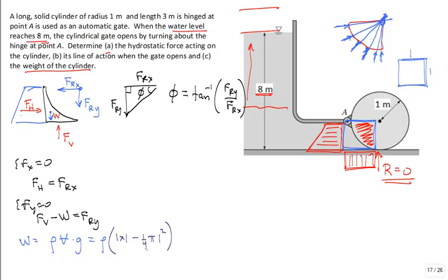That makes sense? Don't go to sleep on me. Are you with me? That's right. And then we have the depth of 3 meters. Put 3 meters. Put 1,000 kilograms per meter cubed, and then 9.81 meters per second squared. And then you calculate the weight, and the weight comes in at 6.316 kilonewton. I'm going to pause. I want somebody to take their calculator and verify this.